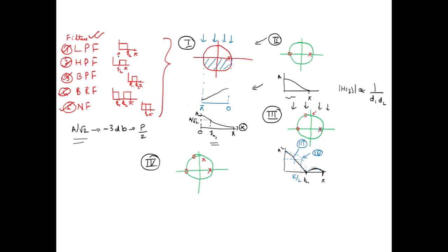If you see the low pass filter, it is having a high value from DC component to FC. FC is the cutoff frequency of the filter. Okay, and in any digital filter, we know that the frequency component would vary from 0 to pi. Okay, ideally it should be 0 to 2 pi, but we usually look into the frequency domain aspects in the positive side. Okay.